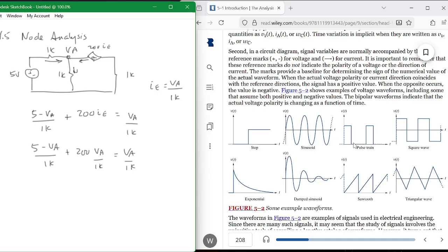Times a diode. Go ahead. I don't know, I take it back. I was going to say maybe you could amplify your square wave so that the bottom of it is at 0, but I don't know if that's it. It is. Yeah, that's an answer. You can move everything up. How would you do that? Use an op amp.